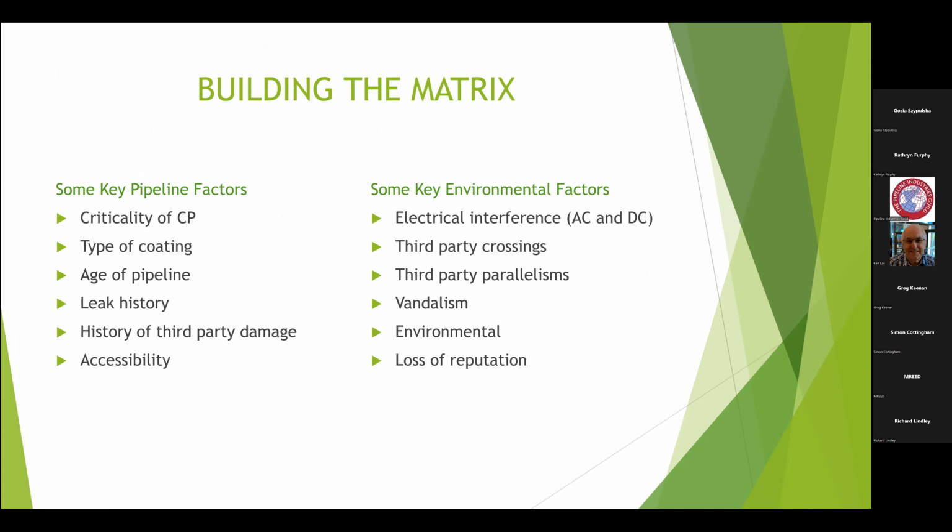In a typical situation, you would take care of the pipeline factors and the environmental factors, and you'd break down your pipeline into sections, because cross-country pipelines can cover hugely different soil conditions and environmental conditions. It's better to break it down. So the first question you ask yourself, well, how critical is cathodic protection?